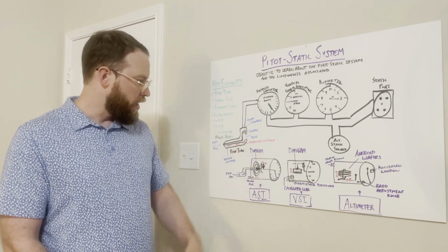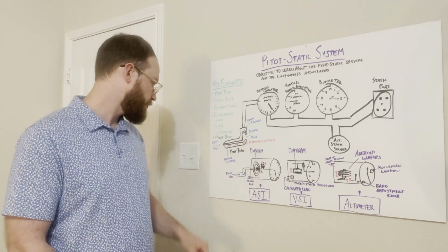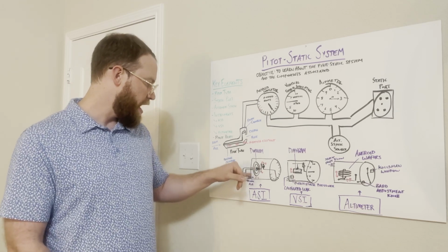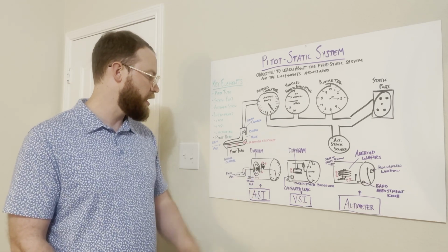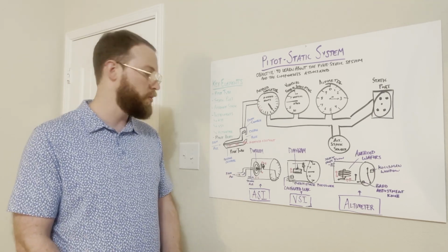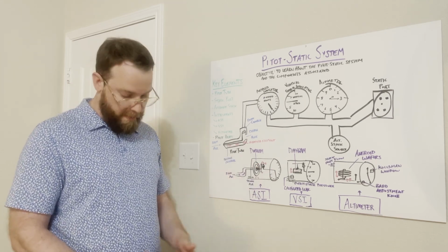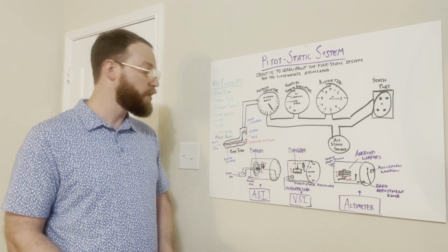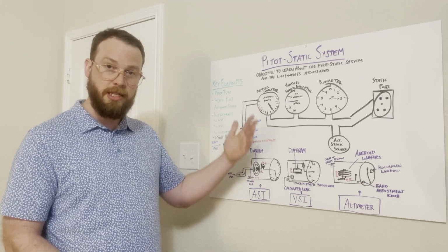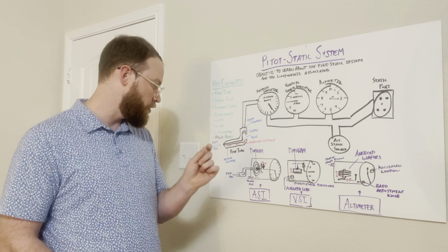So moving to our diagram here, this is going to be an illustration of our airspeed indicator. So here's the ram air that's coming in and goes directly into the diaphragm. We also have a static air reading. Now this, like I said, is a pressure differential instrument that reads the difference between the two and gives us our indication here. So with this diagram, as our air pressure increases, the diaphragm is going to expand, and that's going to indicate a rise in our airspeed. And then conversely, as we lose airspeed, it's going to contract.